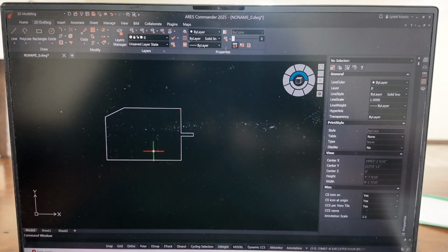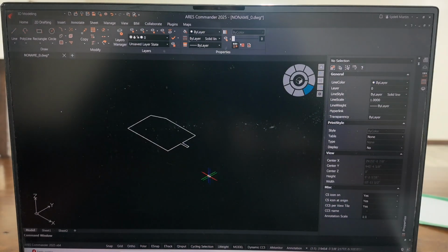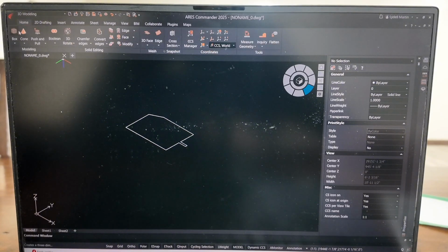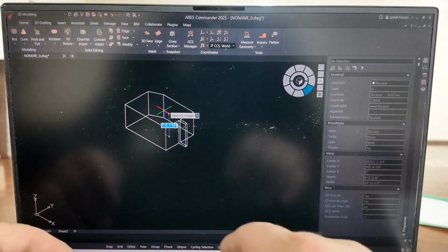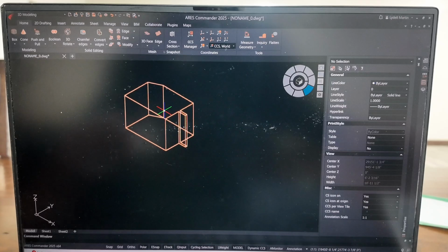So now we're going to go up here in the top right. We're going to select the bottom right view here. Zoom in on that tail. Go up here on the top left. Select the home. Then select the third option, the drop down, the push-pull. Go inside, it shows blue. Left click. And it's 14 by 17, so we want to go 17 inches, enter.